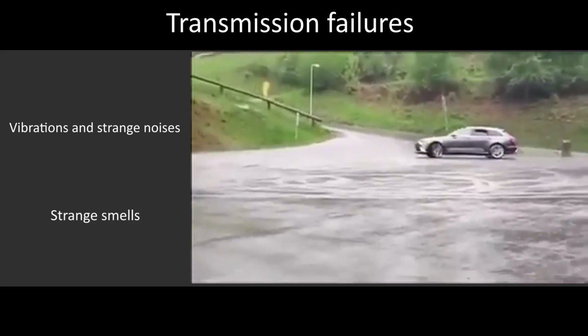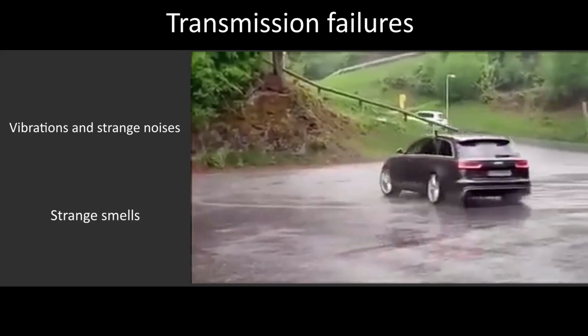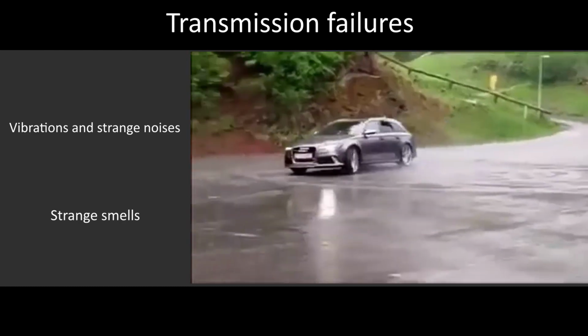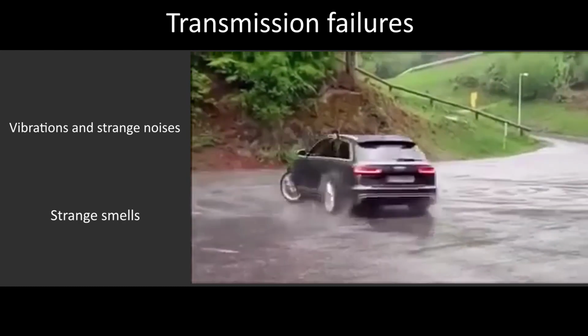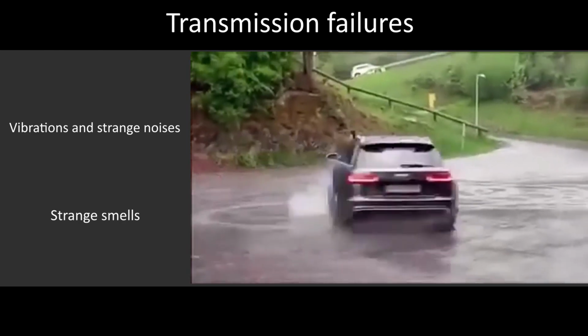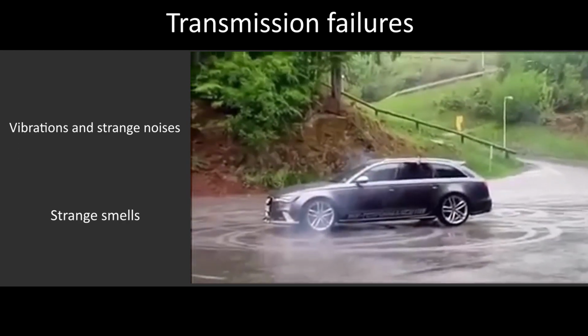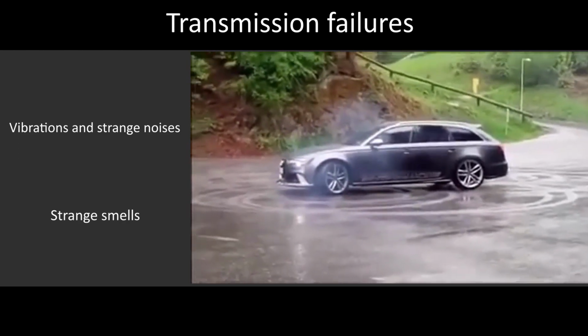Continuing to talk about problems, strange smells are also a wake-up call. Indeed, a burning smell could be a problem related to the transmission fluid. Sometimes the transmission fluid could also start leaking, reducing the pressure inside the transmission, causing damage and extra wear, increasing the risk of overheating.